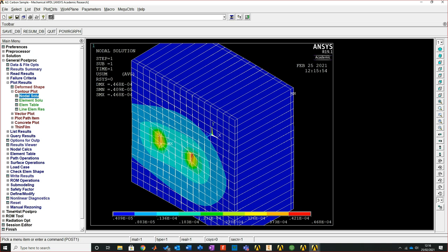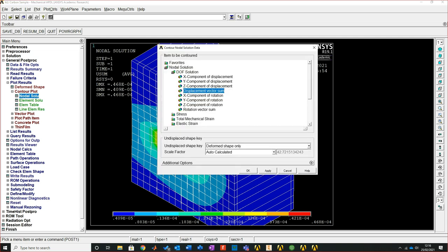We should be able to pick that up by looking at our nodal sum again, but looking at shear stresses that are occurring around it. So what I'm going to look at is my XY shear. Let's have a look at ZY shear. So this is shear that's acting around this side. It's not going to be much, but it's nice to just see it as an overall. So if I bring that back, and go to stresses, and scroll this down. There we go. So I was going to look at YZ shear. Click OK.